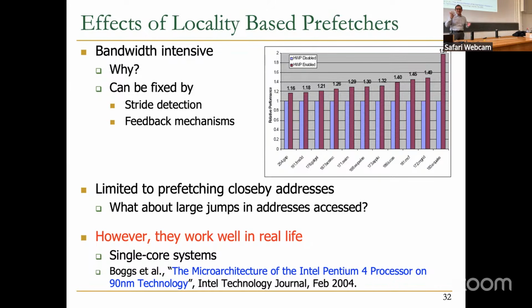So it's good to think about this. You may have multiple regions, and as you keep prefetching in one region, you may start overlapping with other regions that you have created. So you run into an interesting problem with these prefetchers. There are two potential matching entries in the region. So sometimes you need to clean up this region tracking table. Good to think about how these work. Okay, any questions?